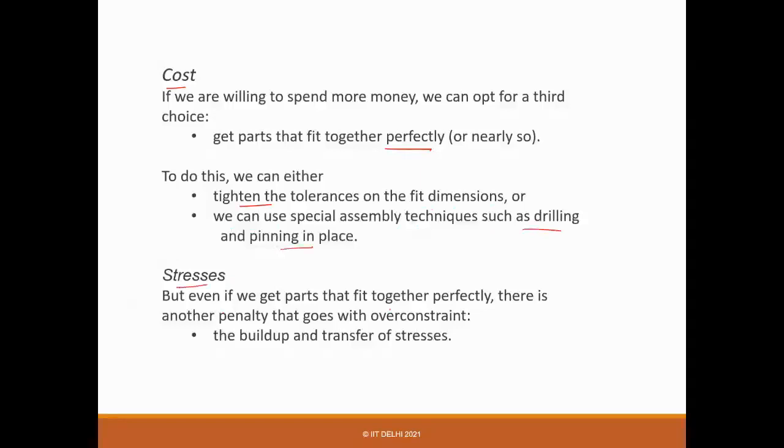Another is the stresses. So even if you are able to manage, suppose they fit perfectly, there is another penalty, and that is called build-up and transfer of stress. What happens if there is a change in temperature, right? What happens if there is a load, right? Since you are not allowing any kind of movement, and it is completely constrained, it will develop some stresses, and that will also lead to failure. So that will be with more examples later. But putting more may not be good.